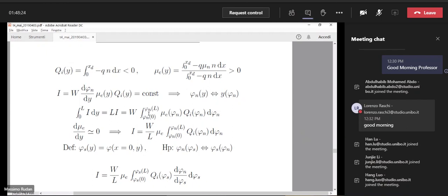It does not change too much with respect to this value. And of course, the gate voltage on the gate is constant everywhere in the channel. It is Vg prime, okay? So the vertical component of the oxide field is constant along the channel, is practically constant.